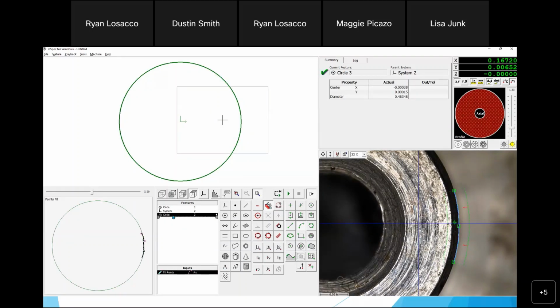So I have one circle made up of this arc. I want to rotate this arc; I don't want to rotate this circle. I right click on that arc and go to rotate, and I say I want an arc every 90 degrees. So I have one arc here, and if I go 90, 90, 90, I need 3 copies of this arc.